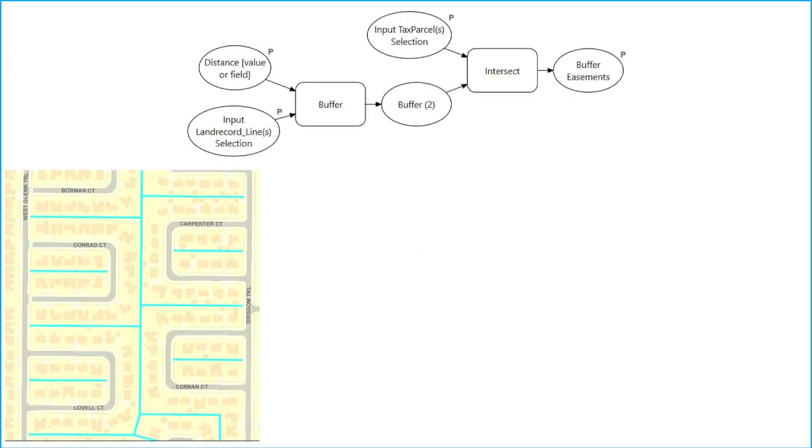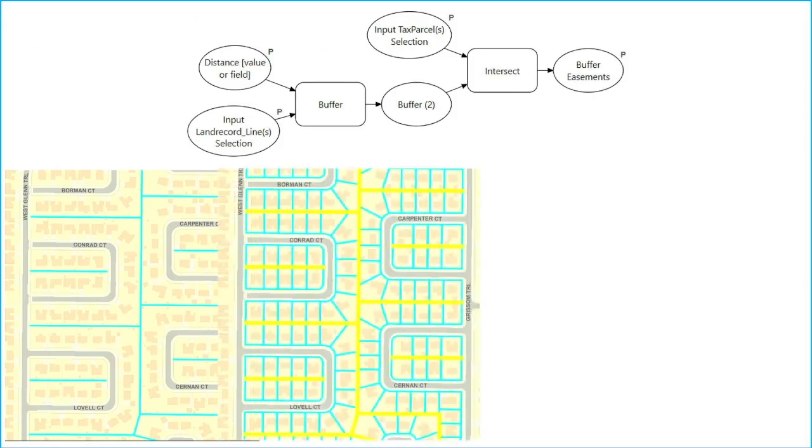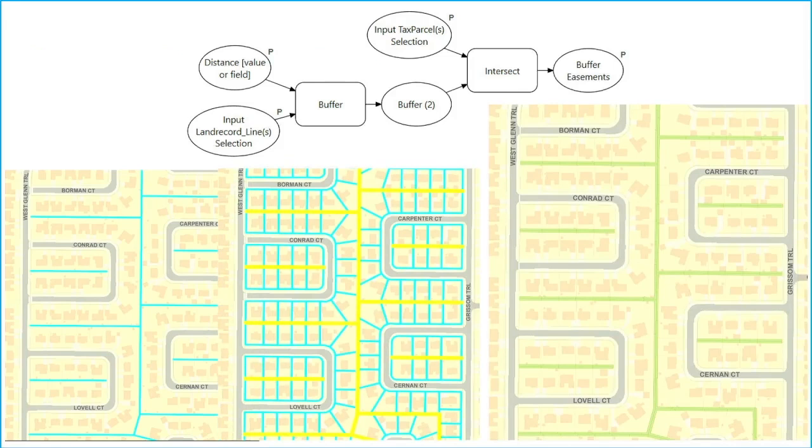Similarly with easements, if anybody's doing parcel mapping or if you're doing easement mapping, okay. Here's an example of taking the parcel lines that we have and then their parcels around them as a selection. I'm just showing in yellow the lines from the original. And we're just doing a buffer of those, let's say by 10 feet, and then we're doing an intersect with the underlying parcels. All of those polygons, there's one for every single parcel at a 10-foot distance.